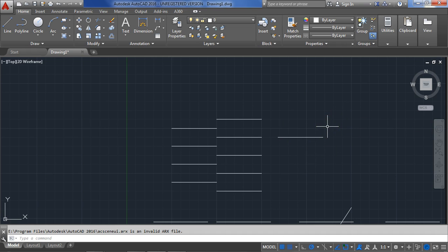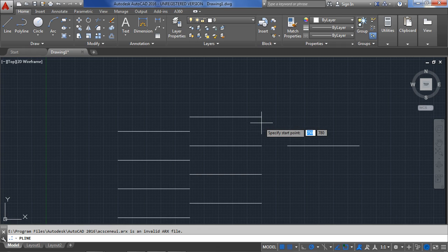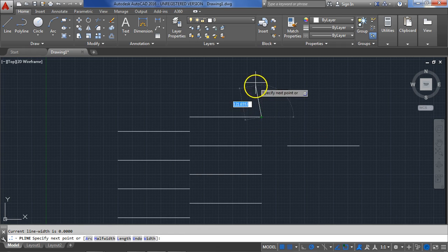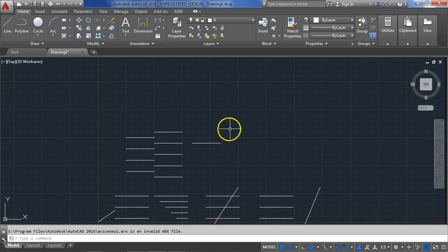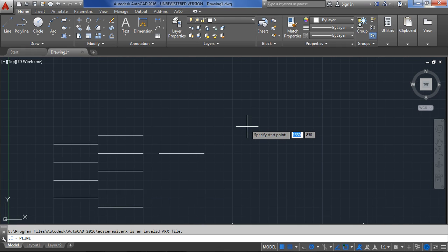Alright, so that's enough playing around with line. How about let's play around a little bit with polyline. Polyline will do all the same things that a line does, it just keeps them all connected. Because they're all connected, you can make closed shapes. Let's see how to do that.